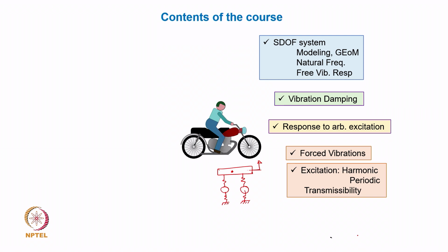So, the degree of freedom assumed was only vertical linear motion. But as we all know, this chassis is a distributed mass, so it has its own mass moment of inertia about the axis perpendicular to the plane. Obviously, it will also have a tilt motion that we never included in our analysis.